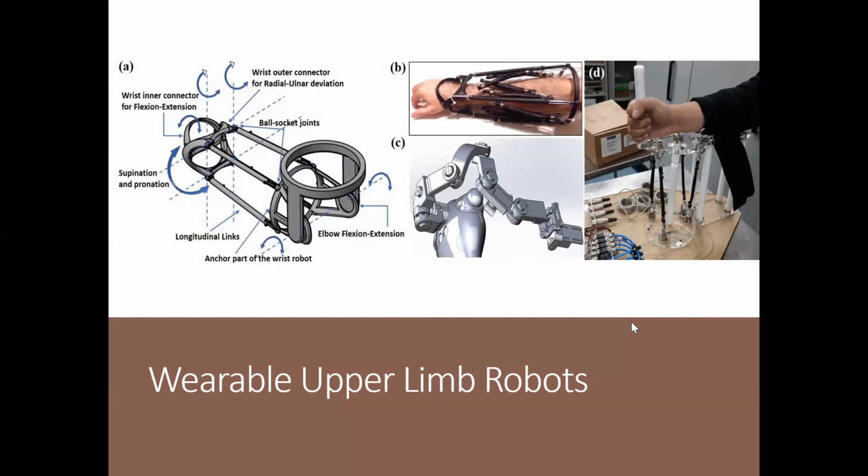The devices that we make are sometimes quite compact, but sometimes they're very big ones. Like, this is complicated, but the shoulder joint has 3 rotational degrees of freedom. So we've got 3 motors here. These are very compact pancake kinds of motors with light weight and high torque, so we call them torque motors.